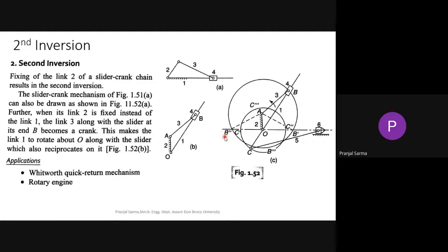That you see in this particular shaper machine. From the name itself, it suggests there are two strokes, the cutting stroke and the return stroke. What is our intention? The return stroke, which is kind of the idle stroke, has to be faster, a quick return. And we get the cutting stroke in a somewhat slower mechanism.